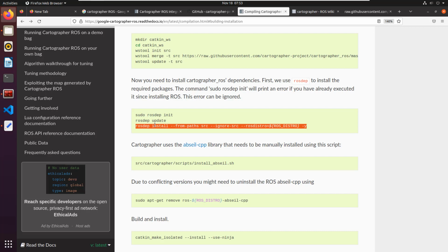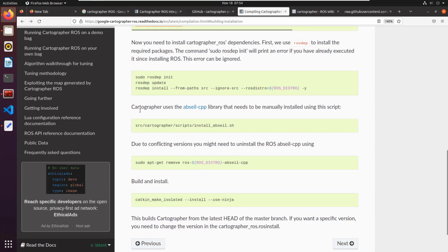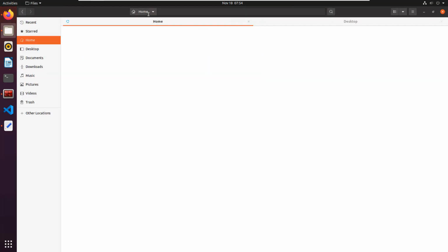dependencies automatically. So you may be thinking, you have created a repository, or a package, and that package has some dependencies, some binary dependency, or some source code based dependency. The source code based dependency can be downloaded using wstool, and for binary based dependency you can simply mention that in the package.xml. If you mention that in the package.xml, these binaries will be automatically installed.